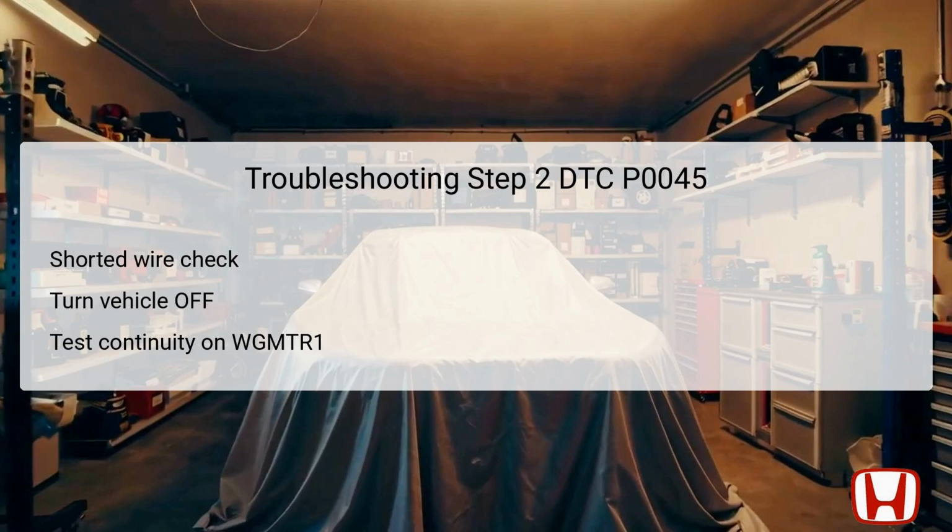Jump the SCS line using the HDS for more than 1 minute to allow the system to reset. Next, disconnect the Turbocharger 5P connector and the PCM connector E80P to isolate the components. Check for continuity between specific test points: Turbocharger 5P connector, terminal number 5, and body ground. Conducting this test helps identify any short circuits in the WGMTR1 wire. A continuity indication would suggest a wiring issue that needs to be resolved, whereas no continuity would lead you to continue on to the next troubleshooting step.